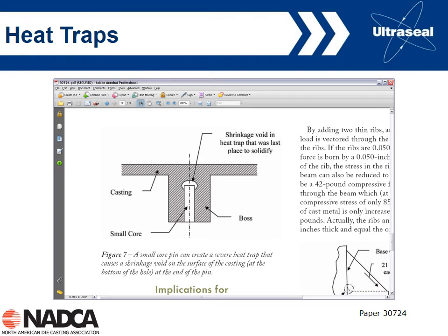For a small core pin shown here, the core pin is going to get very hot, and it can actually encourage porosity. So depending upon the depth of a hole, a core pin can either help in terms of minimizing porosity or actually hurt and cause more porosity.